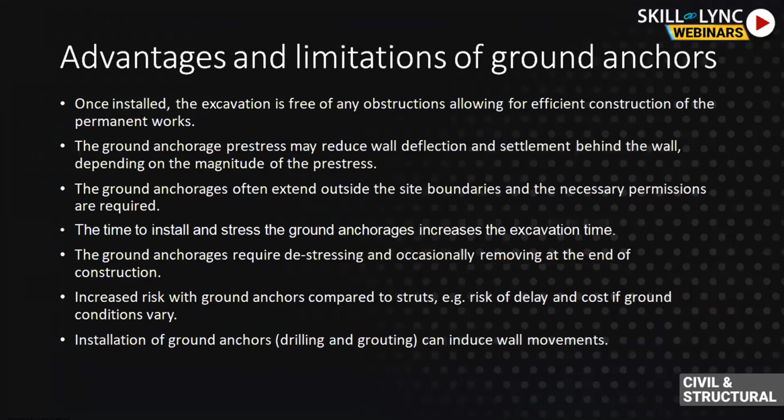Compared to the strut system, in which the strut is placed inside the excavation, it is a little difficult to construct the main structures. But in the anchor system, you have ample space for the construction. The anchors can be pre-stressed to reduce the wall deflection. The ground anchorage pre-stress may reduce the wall deflection and settlement. The ground anchorage often extends outside the site boundary, and the necessary permissions are required.